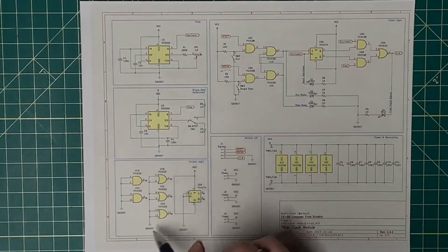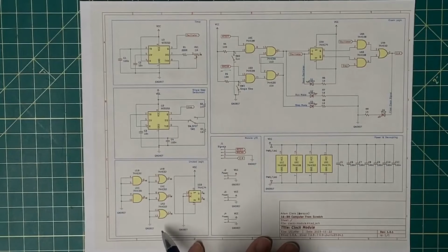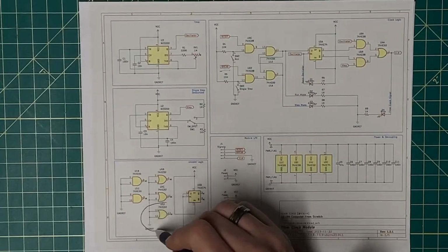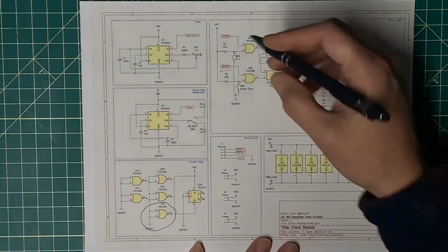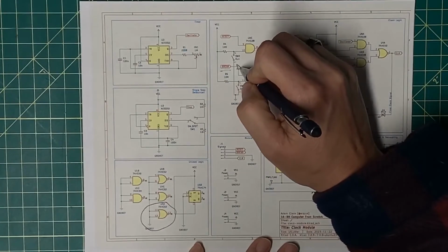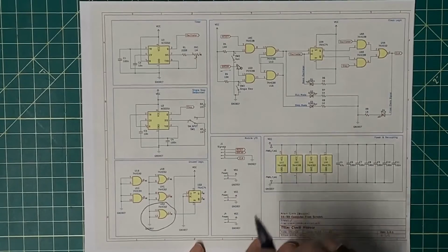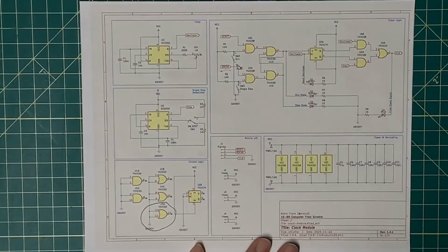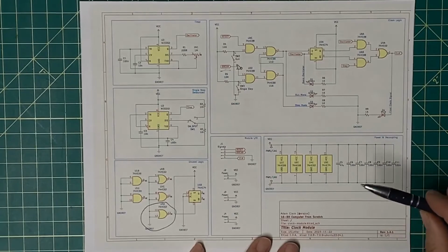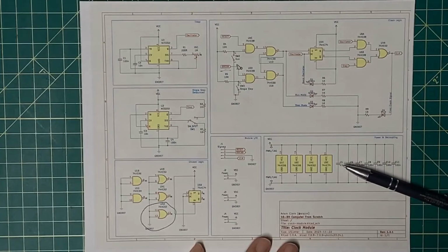I have a number of unused gates down here, and both a NAND gate as well as a NOR gate can be used as an inverter by simply tying the inputs together. So I'm going to take this NOR gate and literally insert that NOR gate in here and change this signal so that it is not inverted anymore, coming off the control logic. That should be a relatively simple change, and I'll get that done and we'll give it a test.